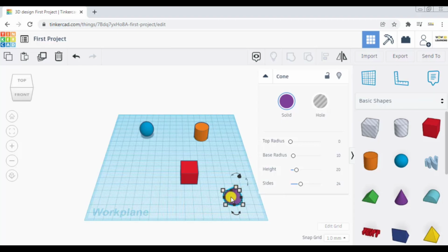Now you have to click on the surface of the object without clicking these dots which you are seeing. We will cover it later. Now if I just click on the surface and drag, you see the duplicate of this object which was overlapping has come out. Now one good thing of duplicate in Tinkercad is, if I click duplicate again, see what happens.